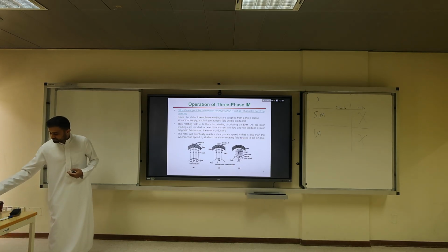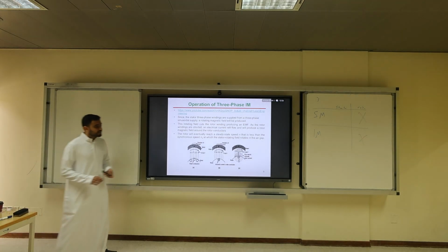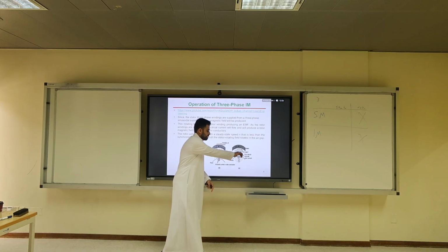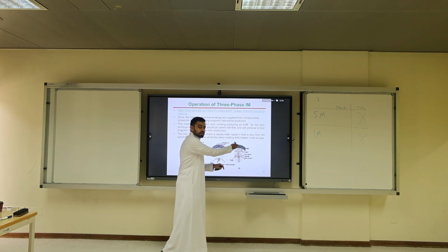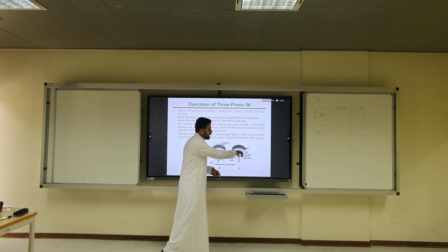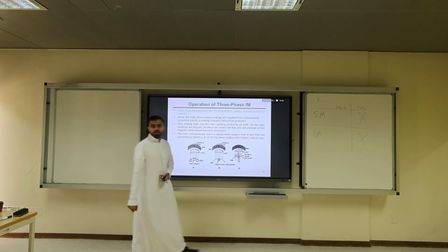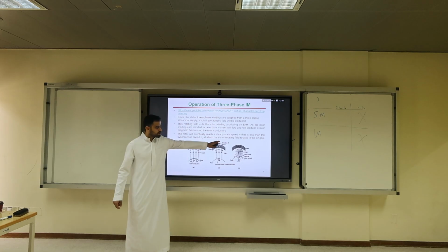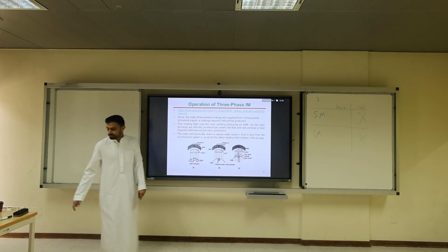Victor, hello. Can you do the right hand rule here? So the right hand rule only, to see the forces. Yes, into the page. So this flux with the flux of the RMF, where does the RMF come from? From the stator. Correct. Here it is opposite. Since there is imbalance between the resultant flux and in the current carrying cable there is a force. The current carrying cable or conductor is the rotor. Stator fixed, force will not impact.